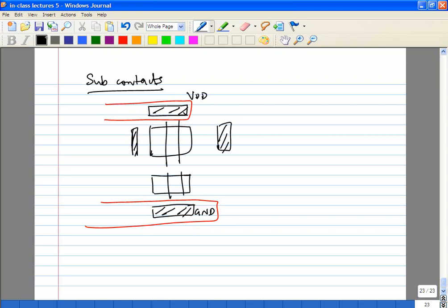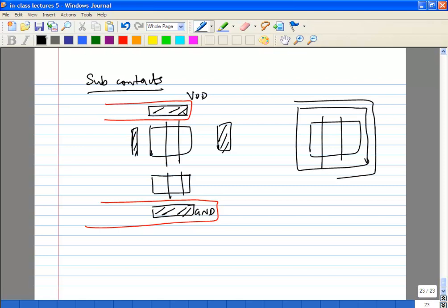However, every process, especially an analog or RF process, will have an RF transistor, which would typically have the transistor and you would have actually a substrate ring around it, and this transistor as a unit will be modeled, including the impedances, the resistances of substrate and so on, everything will be modeled.